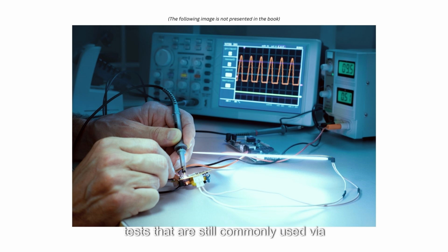The two tests that are still commonly used via JTAG port are boundary scan, within the chip itself, and BIST, built-in self-test. The BIST tests the functional logic blocks within the chip. For PCB design purposes, the circuit designer needs to provide the JTAG port, along with any required circuitry between the port and the JTAG pins.